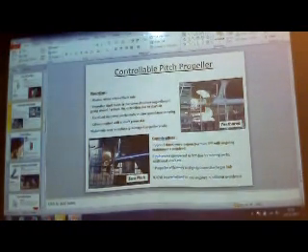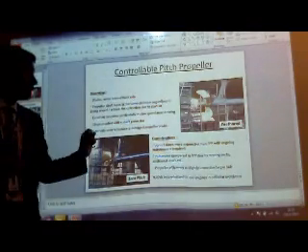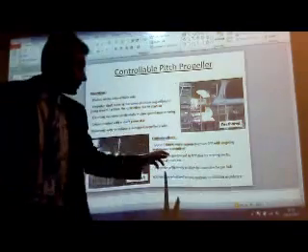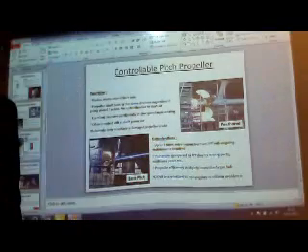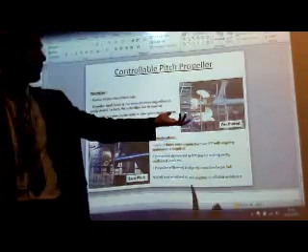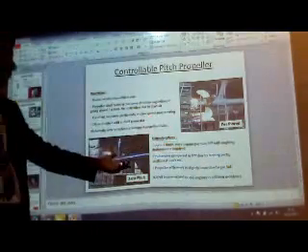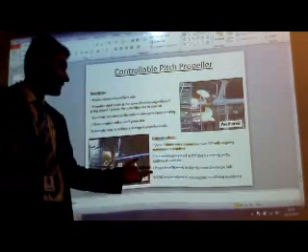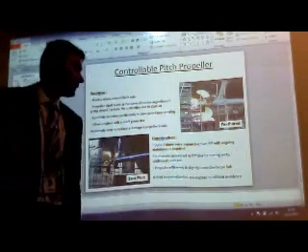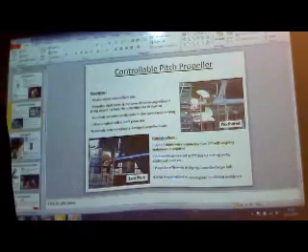Now, another consideration is that it can be up to 3 times more expensive than a fixed pitch propeller. Maintenance is going to be high, with more movable parts. It is vulnerable compared to a fixed pitch propeller due to moving parts and additional seals. Propeller efficiency is slightly lower due to the large hub.